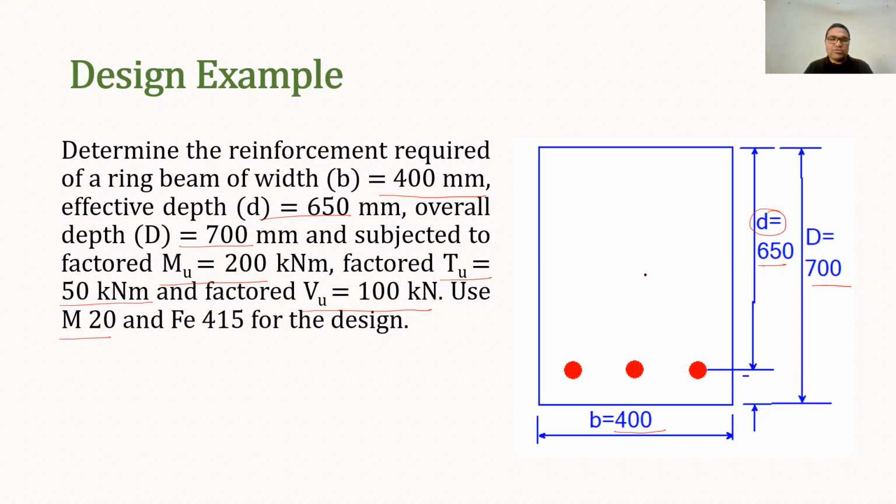Now this is actually a ring beam. So this ring beam can be of any overhead tank. So as I explained earlier also, ring beams are generally subjected to torsional moment, and therefore we now need to find out the reinforcement for this beam.